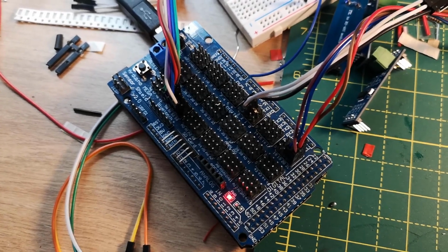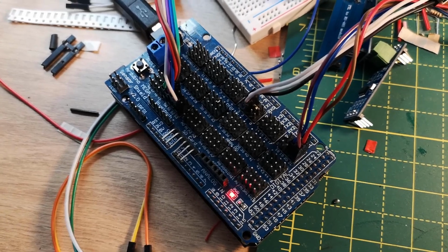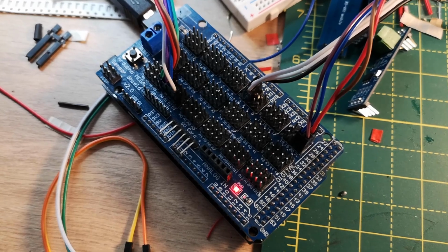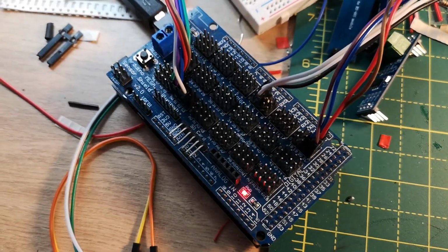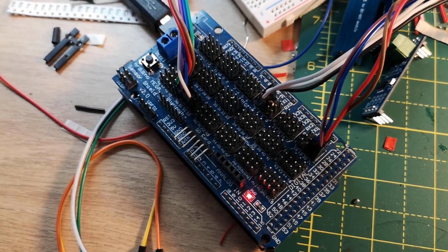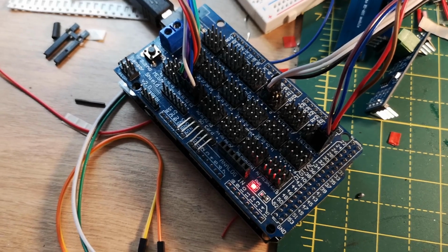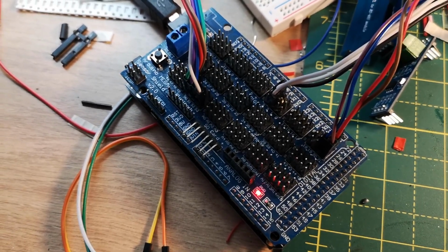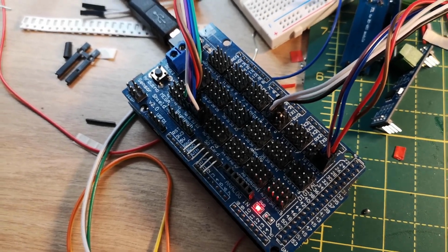But if I'm going to get this thing on the Ethernet, there are a couple of issues I'm going to need to overcome. The most prominent of which is the Arduino doesn't have an Ethernet socket. There are Ethernet shields available, but they're all designed for the Uno. They might well work on the Mega, but they wouldn't be compatible with this sensor shield, the thing that's got all the pins on the top. So I would be really restricting and changing how I work if I was to buy one of those shields.